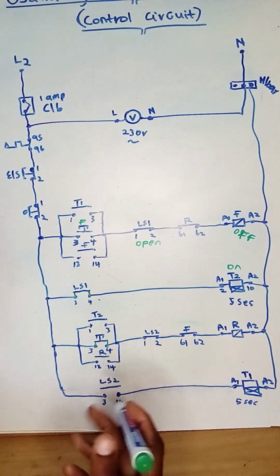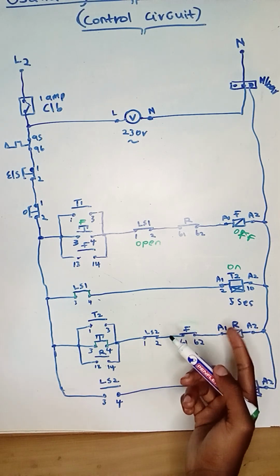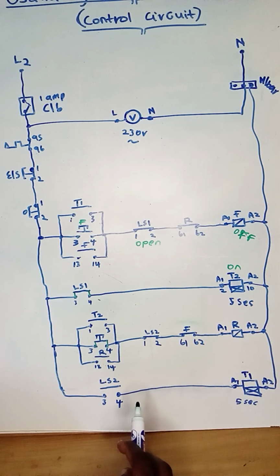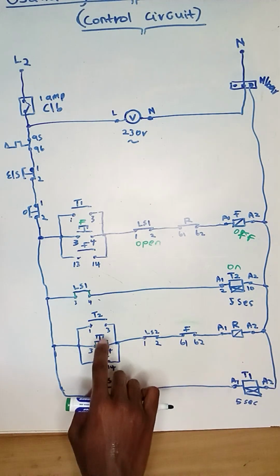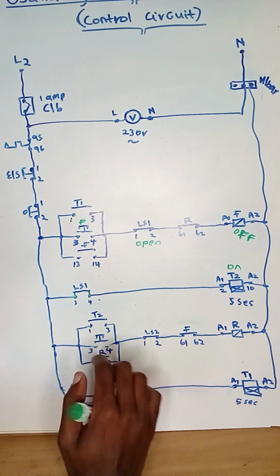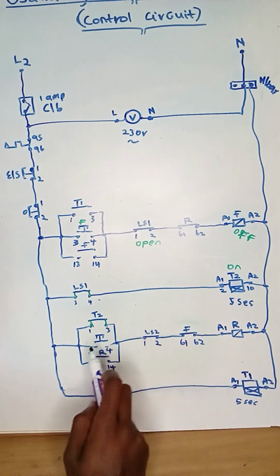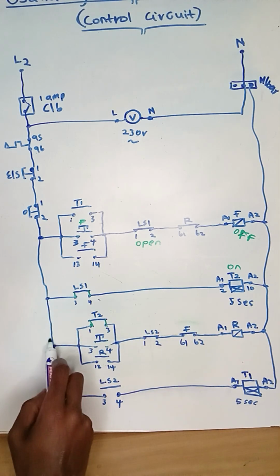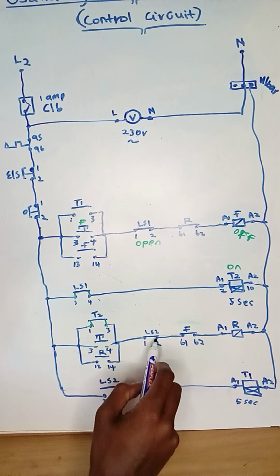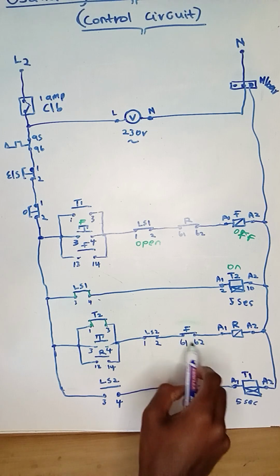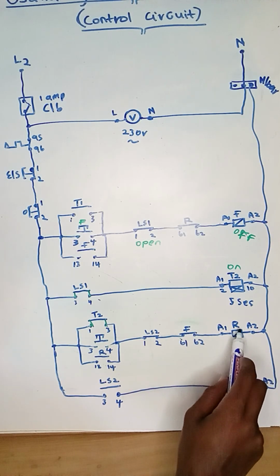or did what you wanted the switch to do. So right now, when timer 2 is energized, after 5 seconds, it will affect its auxiliary contact. The auxiliary contact of timer 2 is this one here, a normally open contact, which means right now it will be closed after 5 seconds. And when it's closed, current will come from here, find a closed contact and flow down here, all the way to the contact of limit switch 2 normally closed, which it will flow through, and finds the interlock of forward closed, which it will flow through, and all the way to A1 of the coil of reverse.